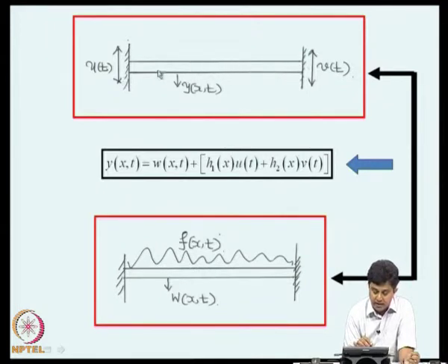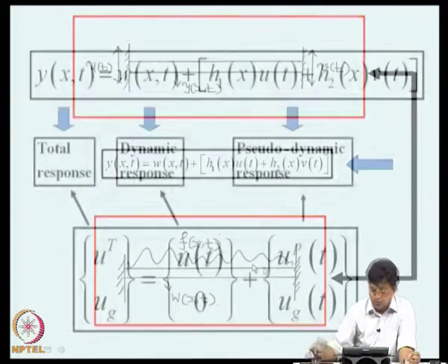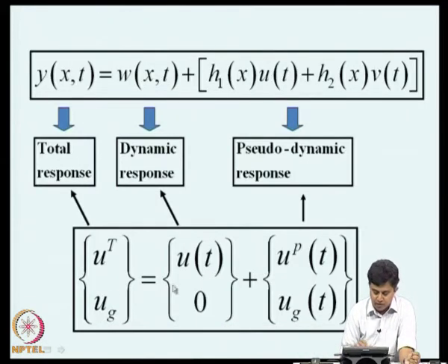That is, in this structure, without the inertial terms participating in the solution, we still get certain displacement and stresses in the beam due to differential support motions, and that is a pseudo dynamic response where inertial effects and damping effects are not included. This is a dynamic component where inertial components are also included, but the supports are now not moving. So, this is, as I already said, analogous to what we saw when we studied discrete multi-degree freedom systems undergoing differential support motions.